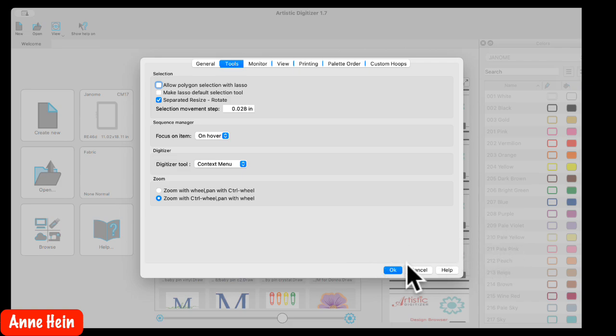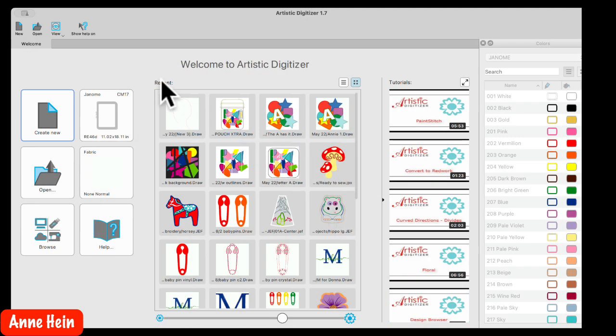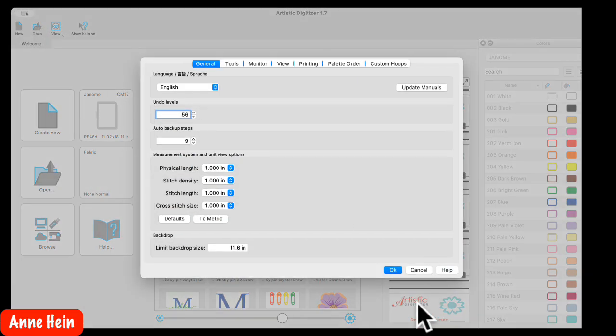And if you're on a PC, you're going to go under Tools, Tool Options, and then you'll see that same screen. Now, the thing under that same screen, which is nice, if you haven't found it before, on the first page, you can change your measurement from metric to imperial. Normally the default says 2 imperial, and if you want to go to inches, you would click there, and it would now say 2 metric. If I wanted to go back to metric, I would click there. All right, so if it says 2 imperial, click it, click OK, and it'll change your program for you.